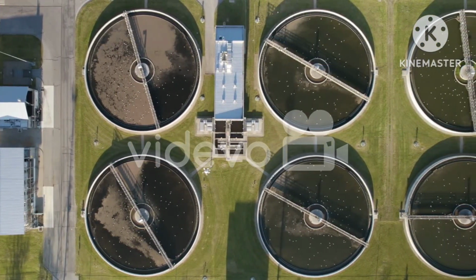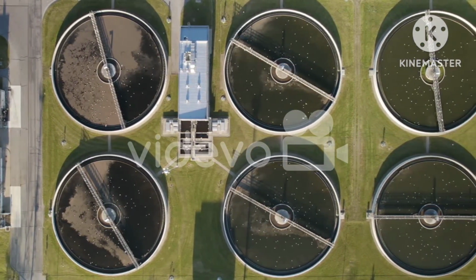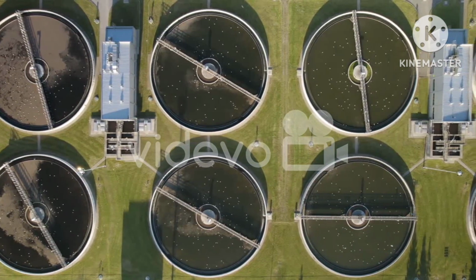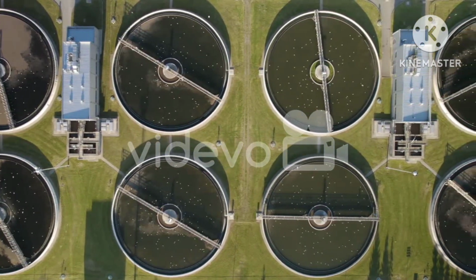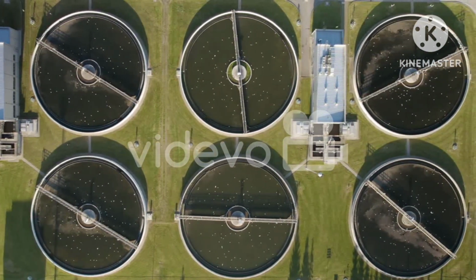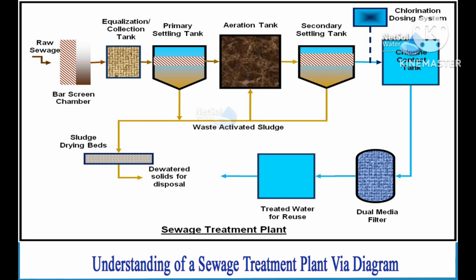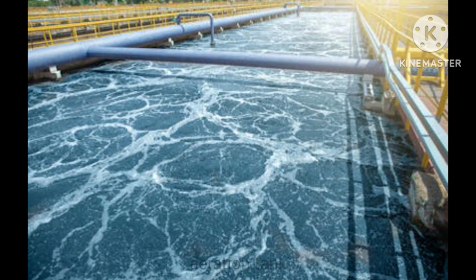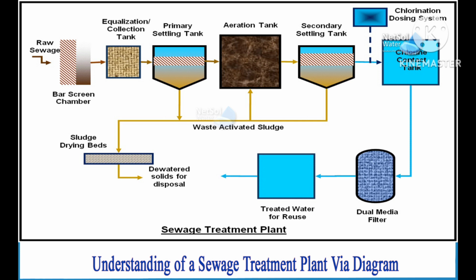The third stage is primary clarifier. Initial separation of wastewater and solid organic material. Sludge or organic solids are pumped to a digester or other location for processing, drying, and removal after they sink to the bottom of the tank. The fourth stage is aeration. To promote the conversion of NH3 to NO3 and to give oxygen for bacteria to continue to multiply and develop, air is pumped into the aeration tank or basin.